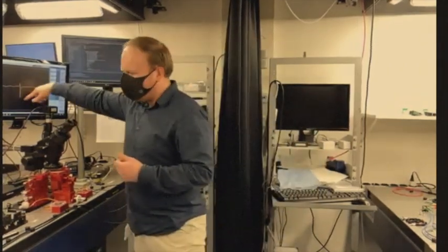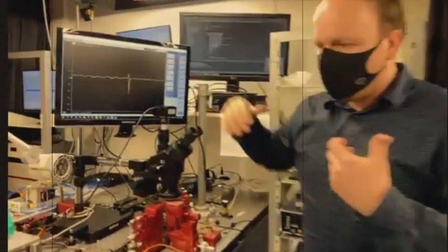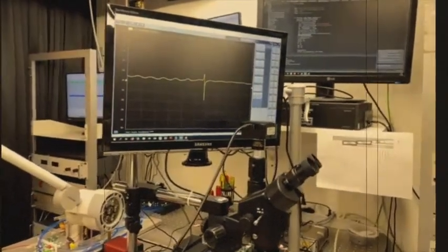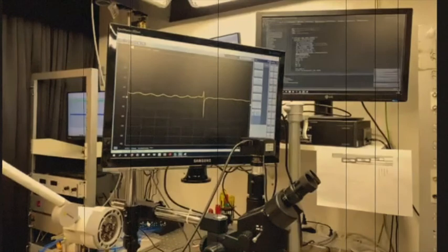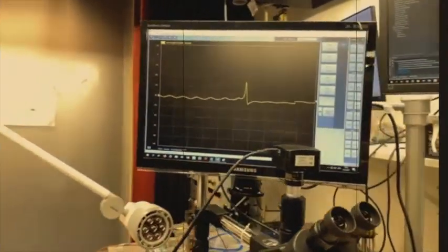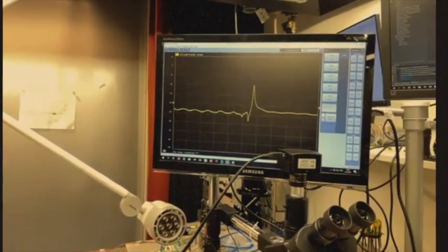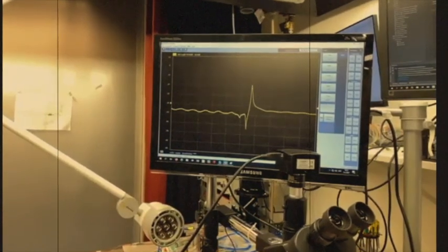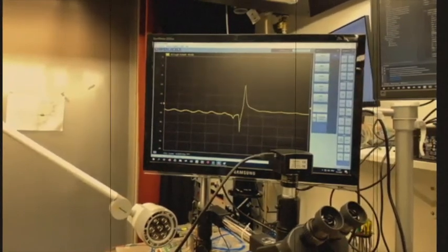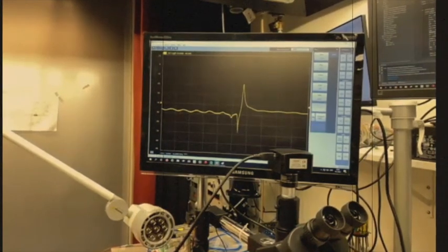We can see, for example, here I've built a microwave photonic link. By playing with the way I modulate my light and then amplifying a part of it, I can create a notch filter like this, or by changing the modulation, I can switch from a filter where I remove one signal to a filter where I increase a signal. So this is something you can use to remove a jammer, for example, or to amplify a signal that is of interest to us.